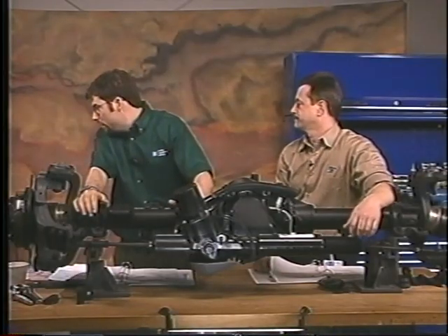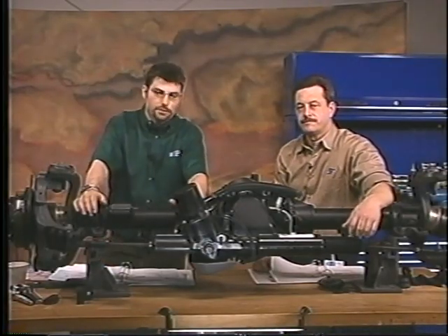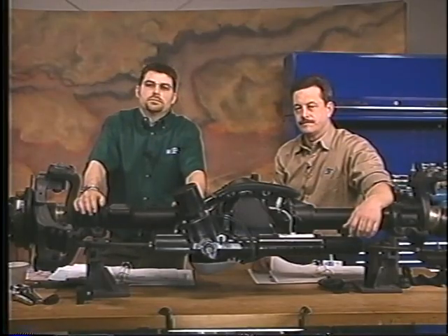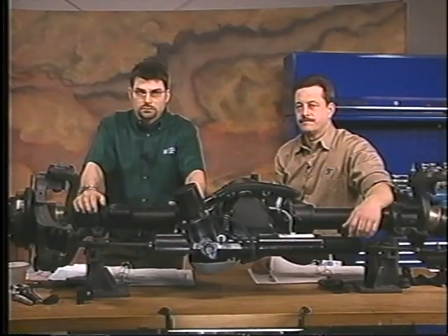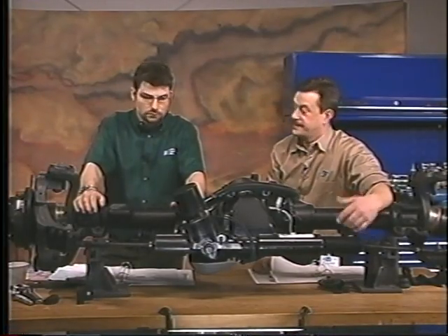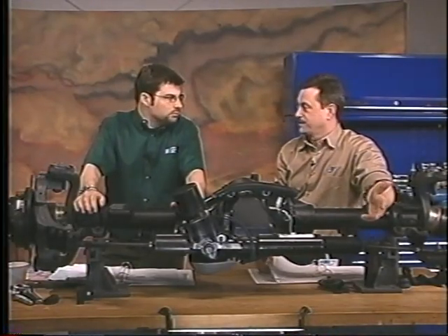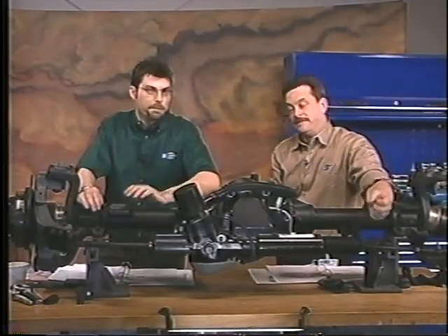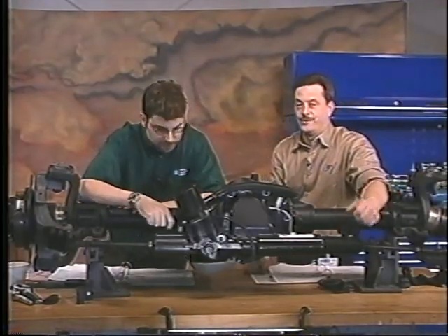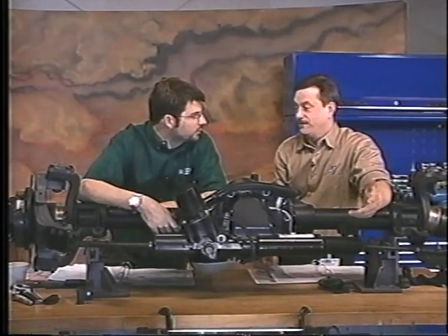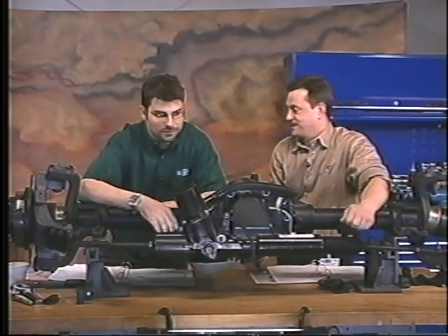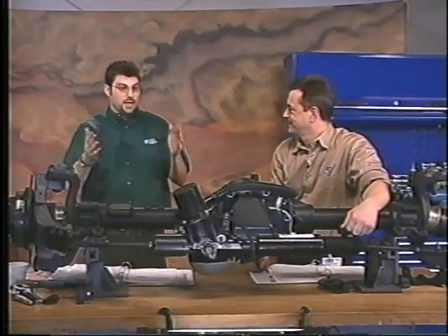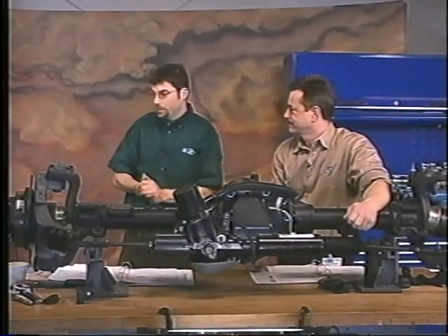Now, next we have Eric calling in from Roy Robinson Chevrolet. Next input, go ahead. That vehicle sensor definitely does know which phase to operate in. Yeah, that's a good point. We can talk a little bit about what we're using those for as well. The steering position sensor is telling us what direction we're turning the wheel and how far we're turning the steering wheel. Obviously, that's going to have something to do with how far we turn the rear wheel in the direction. It's probably pretty important for the control module to know. And then we've got the vehicle speed, because we've got that 45-mile-an-hour cutoff, so we have to use vehicle speed for that input. You bet.